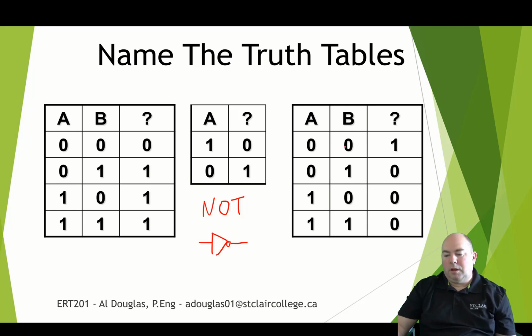This one over here. Let's do this one here first. So 0s give us a 0. If we have B, or if we have A, or if we have both, that all gives us 1s. That is the OR. And over here, we have a 1 with 0, 0. That is the only combination that gives us that. You can look, and that is the opposite of this first one over here. That is the NOR.